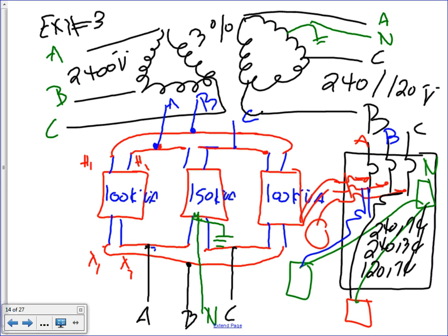But yeah, a 208 volt single phase motor, we can't use it. Can you use that on phase B? If you use it, it will run, yeah, but it will screw up the system. You're not supposed to use it. Have you ever used that? Oh my God.